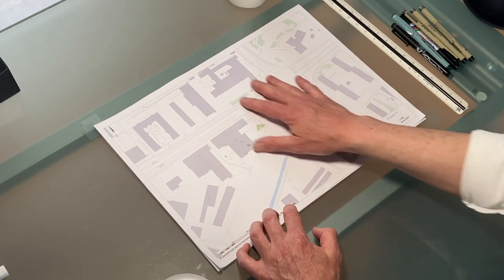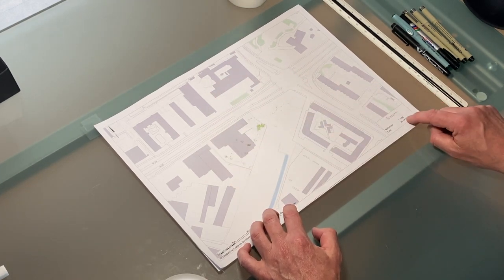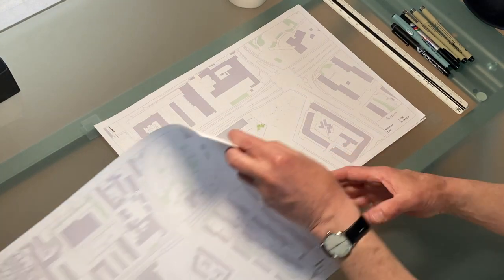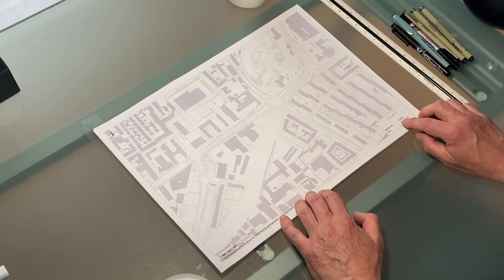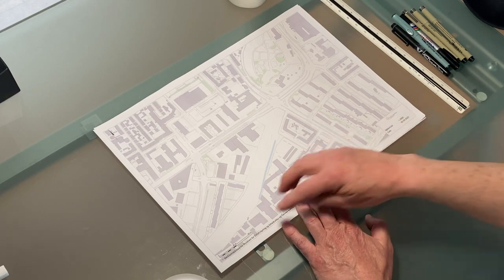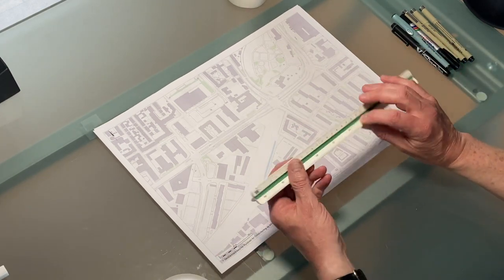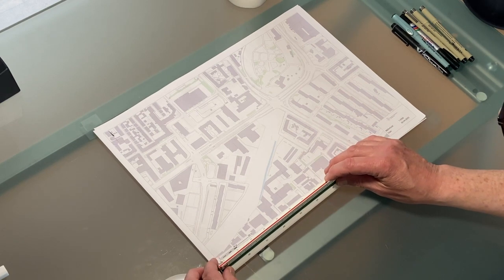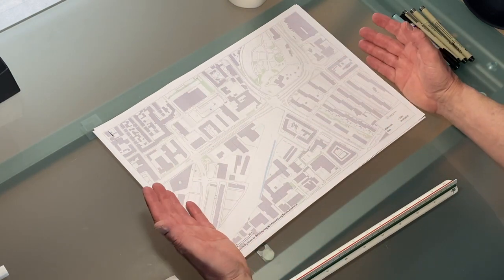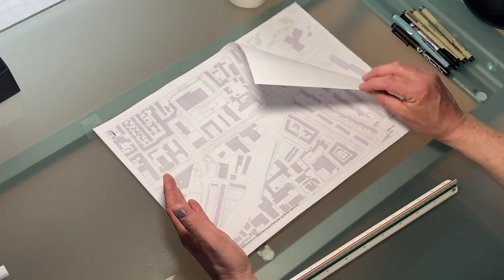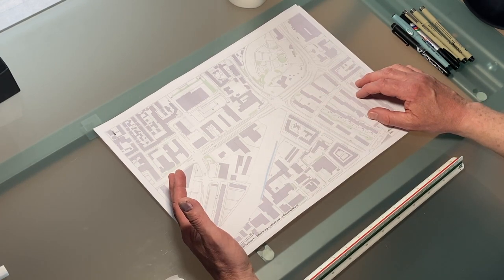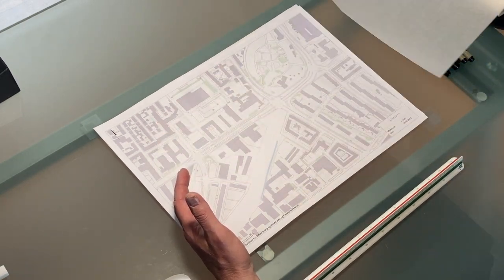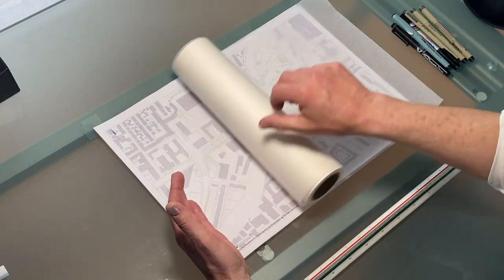So while we may be doing the majority of our sketching in scale 1 to 1000 in this case, we may also want to have a slightly larger map and a smaller scale. Scale 1 to 2000 is this. So now 6 centimeters equals 120 meters. So we have to find scale 1 to 2000, and again we can see this is exactly 120 meters. This may give us a larger area, and please note that I'm working here always with A3 sheets. In Europe they come out of the printer very easily, and it fits with the width of the 30 centimeter tracing paper. So that's a handy size.